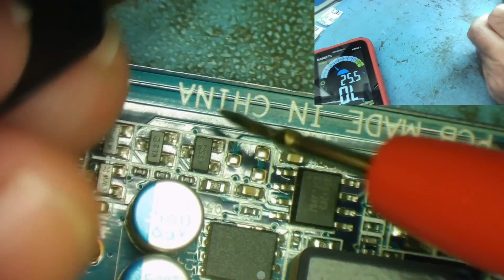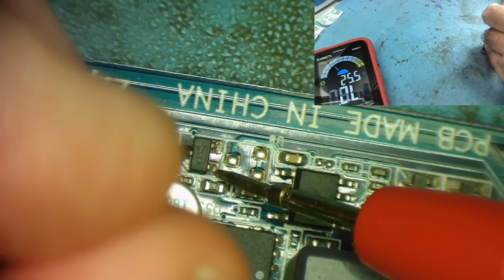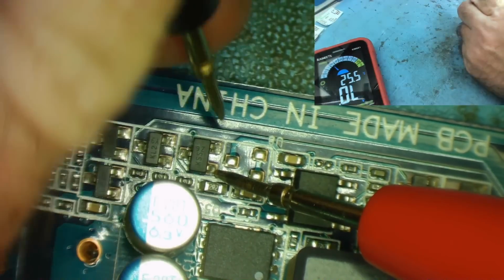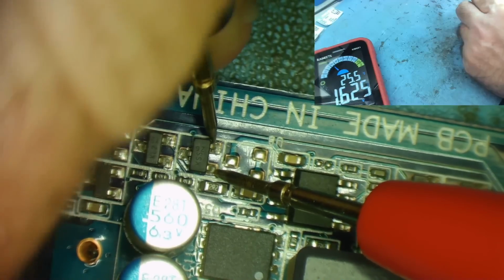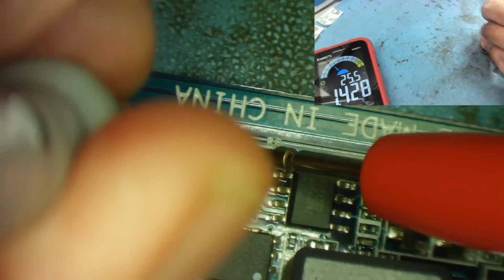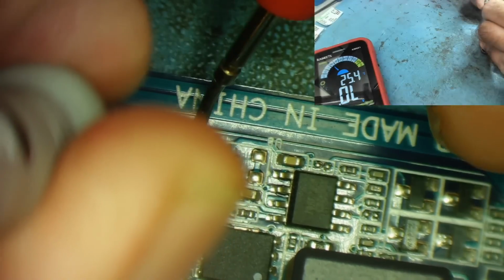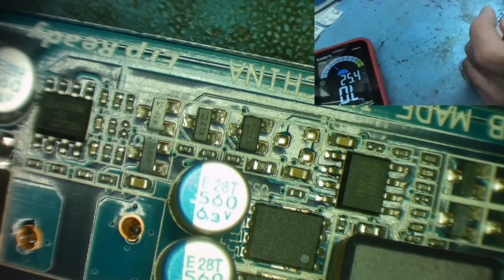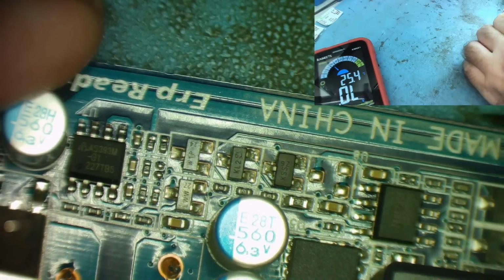But it's not a very reliable way of testing, to be quite honest, and you will find, I mean, that's the diode junction there, and is there one here? No, but again, these could be just diodes. These could literally just be diodes. So I'm sure you can see from what I'm showing you, it's not really practical to test for MOSFETs in circuit unless they are short circuit.